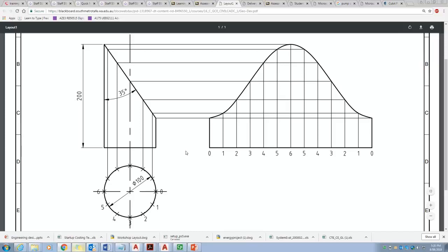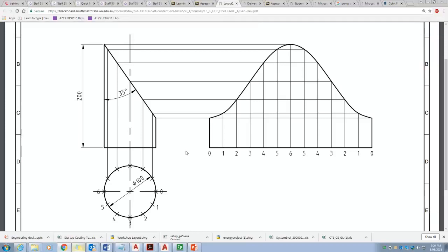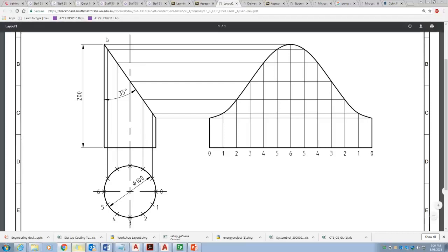So generally what happens in the fabrication office is that you know that minimum sheet size. Then once you get this profile one-to-one onto the sheet, you get your points along the spline, then use a punch hole to get those intersection points. Remove the sheet, cut the sheet metal along the curve and fold it to get a tube-like section. But this is actually a tube with a section of angle 35 degrees. 35 degrees here means it's actually 90 minus 35, 55 degrees here.